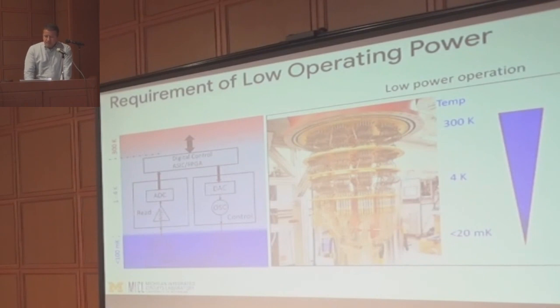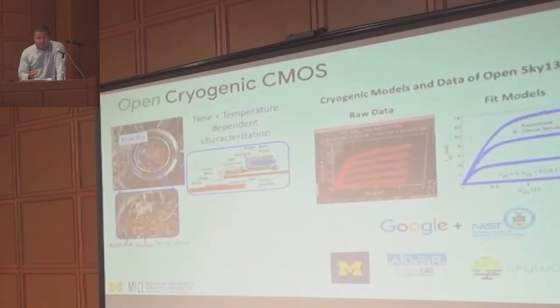Another consideration is power. The dilution refrigerator has a limited cooling power, so as we go down in temperature, the control system needs to be within milliwatts in terms of power budget. So we have achieved some initial results, including the release of prior models in SkyWater 130, and we're publishing a work with the full cryo-CMOS models in ICCTS this year. Together with these partners, we have developed test chips, tested them, and created the compact models that can be used for